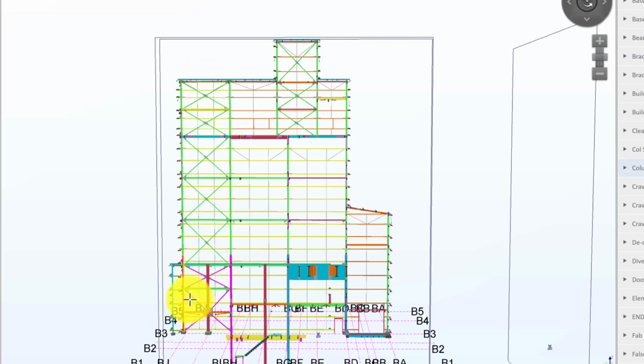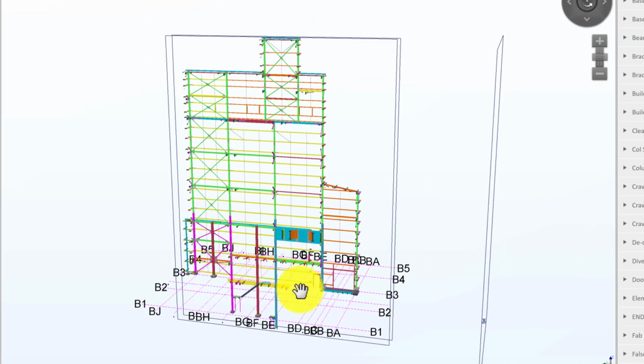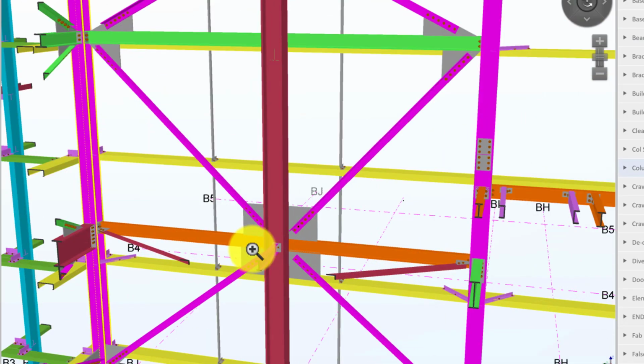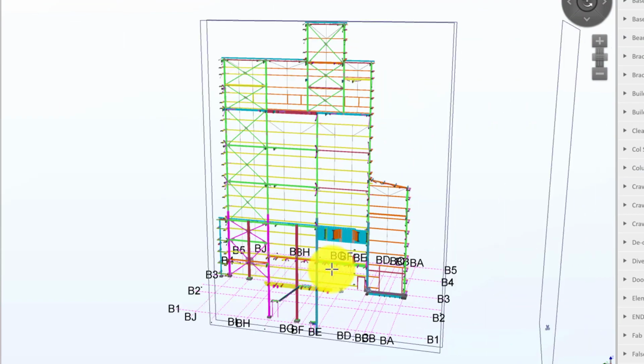Now, this braced bay being relatively narrow had very high compression and tension loads when the wind blew on this, or there was a small amount of seismic activity in this area. So you'd have very high compression loads in this section and very high tension forces in this. You can see some quite heavy connections here that were designed for that.